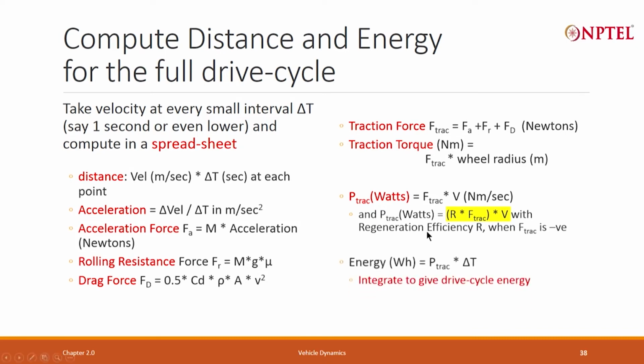Then you compute the energy requirement. What is the energy requirement? The power you have got for 1 second. Integrate the power, or take the power in the beginning and power in the end and subtract it, divide by 2, multiplied by 1 second, that will give you the energy. So, you have the traction force, torque, power and energy.